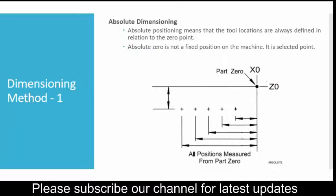See, now absolute dimensioning. Suppose that we are having a job. There are 2 ways by which we can do programming: one is absolute and one is incremental. So we must know the dimensioning pattern of the absolute and incremental. And in the absolute way, the dimension is being measured with respect to a single 0 0 point.